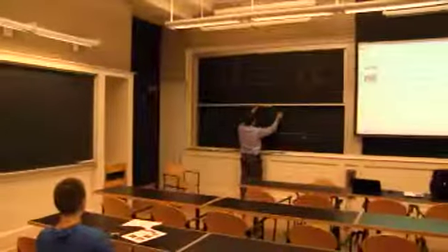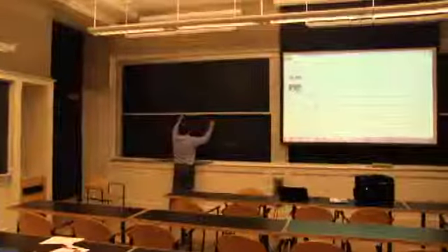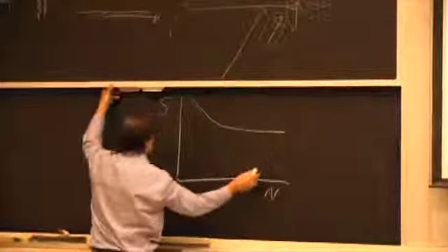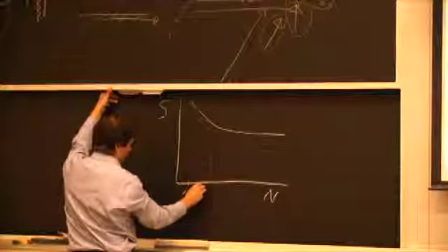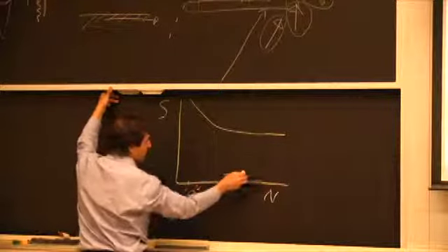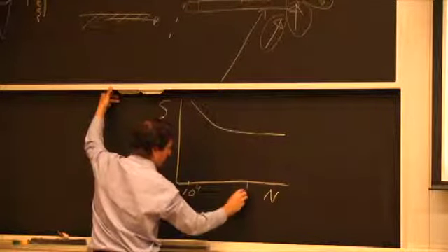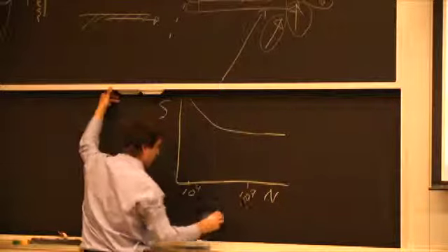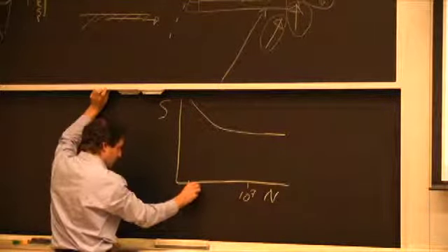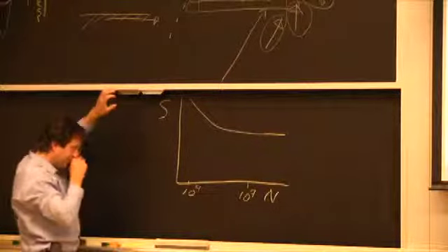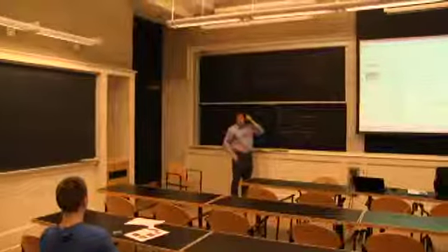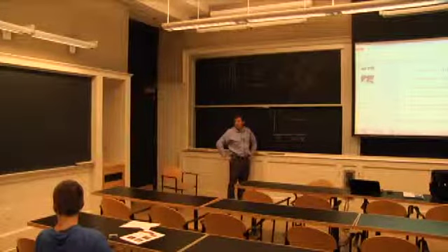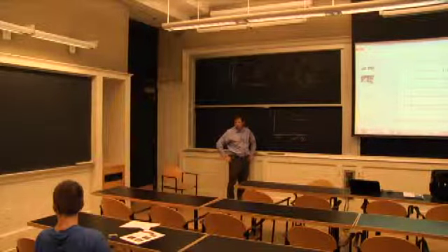That's for the members. The welds, you assume will have defects. They won't all be made perfectly. On the SN curve for steel, at 50% of yield you'll have infinite life. And Dr. Belmar was saying he knew he wasn't going to go to millions of cycles, so he actually could have an even lower safety factor, because the actual stress that's going to cause yielding is going to be much higher. And the code has already given him a factor of 2. So if he's designing for low cycle fatigue, your safety factor is even more conservative, but they use the factor of 2 for fatigue for bridges and buildings.